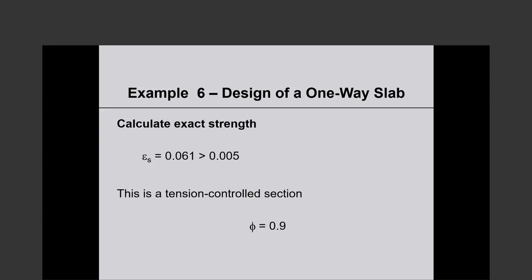And by providing the minimum amount of tension reinforcement, I believe we have taken care of that. This should be my answer. Think about whether what I'm saying makes sense. So there is an effective upper limit imposed by the minimum reinforcement ratio that we have to provide, would be my answer.